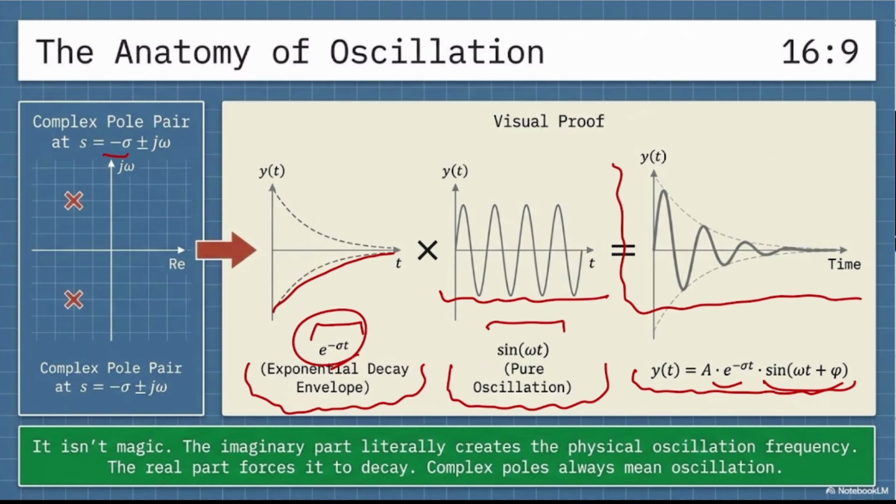The very first thing you may have in mind is: how do you know your system is stable? If you look at this hypothetical condition, we can see that our poles are completely on the left side of the S-plane, and that was a thumb rule. The rule says that if your poles are on the left side of the S-plane, your system is going to converge and reach the steady state. On the other hand, if I have my poles on the right side, my system is going to have constant oscillation or increasing oscillation, which is not good, and it means our system is not stable. So as you just saw, it's not just magic.